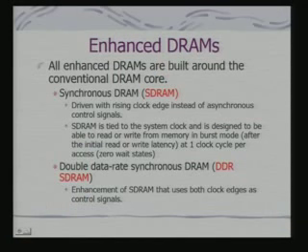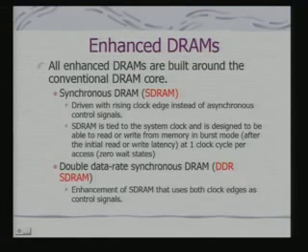Now, variations of these to speed up the DRAM access have been suggested, which is synchronous DRAM or SDRAM. In fact, in many of the PCs and others today, when you buy memories, you buy SDRAM. The DRAM control signal is based on the rising clock edge instead of asynchronous control signals, that is RAS and CAS. So, SDRAM is tied to the system clock or the bus clock and designed to read or write from memory in burst mode after the initial read or write latency, at one clock cycle per access.